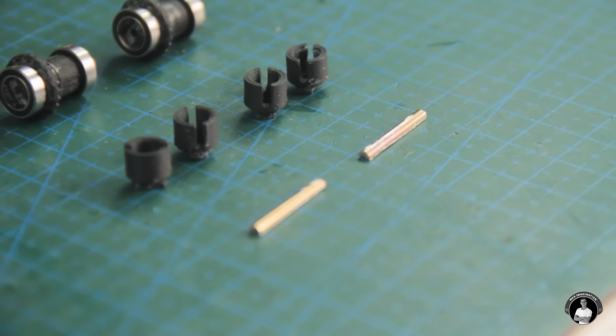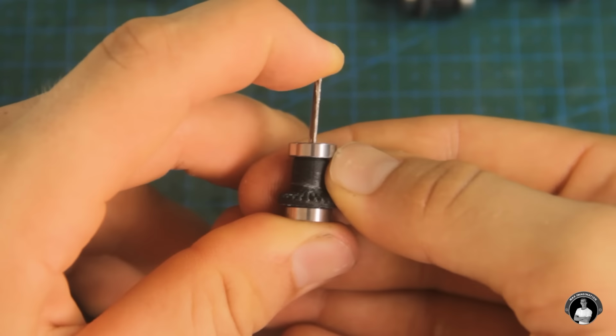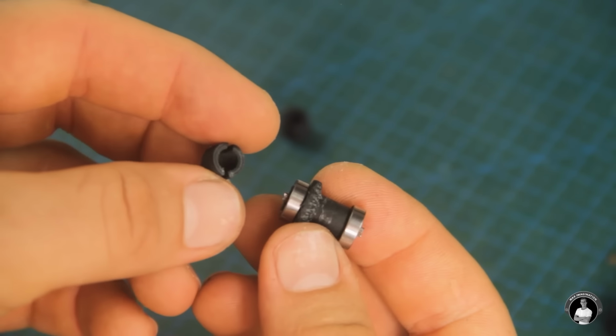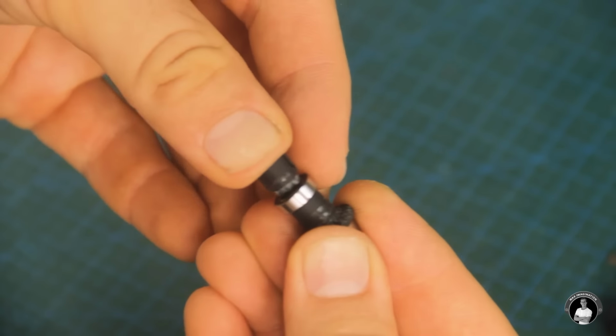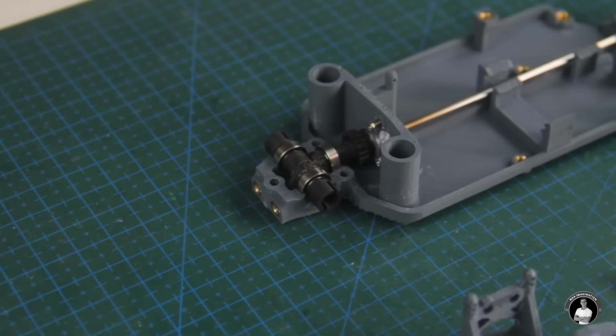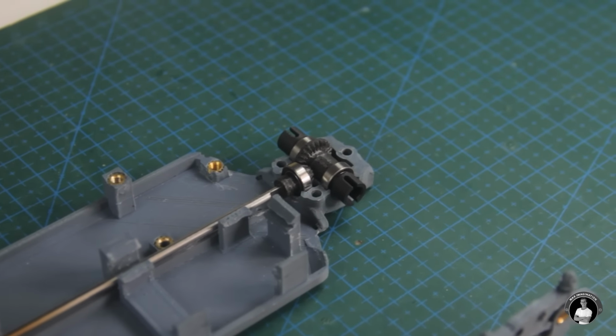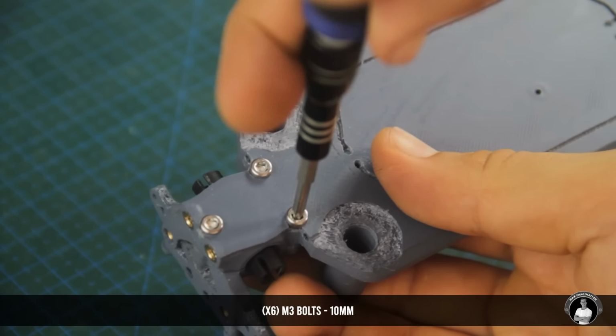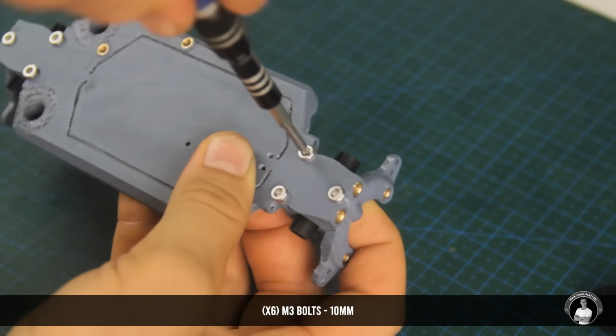For the front and rear axles, we'll push in a shorter rod into each spur gear so an input shaft cup can firmly connect to each end. However, I still recommend securing these on with the addition of super glue. Now these two can be secured into their gearboxes with the corresponding upper housing pieces, closing them up with the help of some M3 screws.